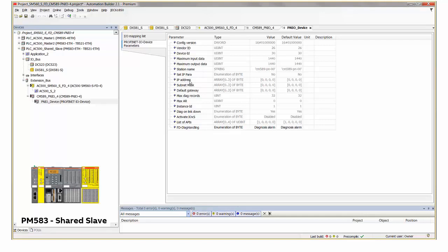For your information, the virtual LAN functionality is also supported by PROFINET. You have to configure this virtual LAN tagging on your network switches. You may need managed network switches and activate related ports on them to be able to send these VLAN tagged telegrams to proper LAN network paths. However, we have to take into account that PROFINET requires in the beginning an untagged network to be able to parameterize all participants. So with VLAN tags, one has to pay special attention to the network switch configuration for PROFINET.